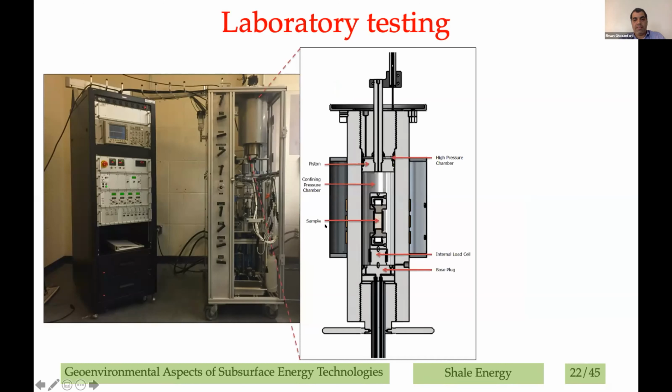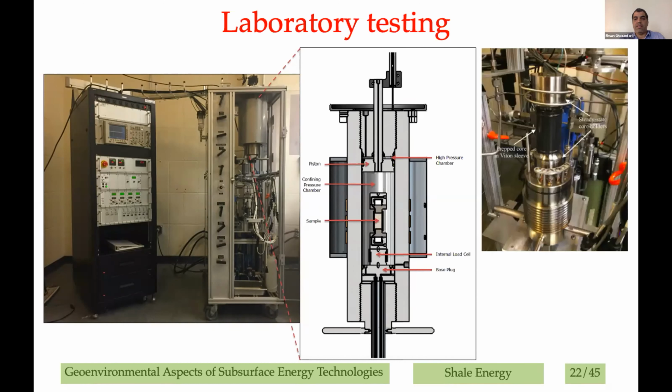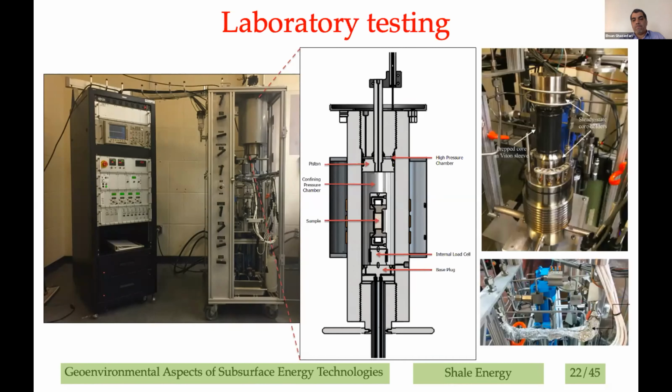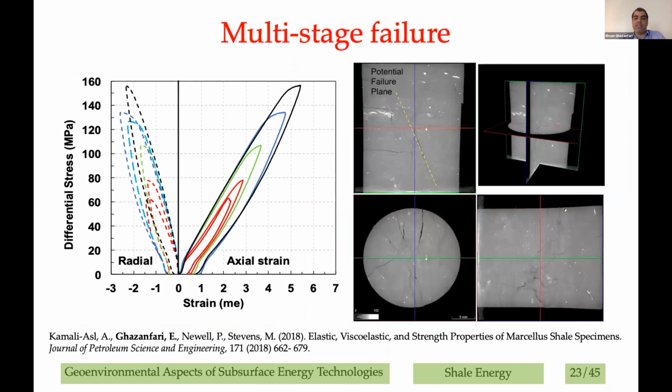So it's similar to a typical triaxial setup where you subject the specimens to confining pressure and axial pressure, and there's also pore pressure, but with higher pressures so that you can study relevant conditions in the lab. These are images of how you can set up the specimen and how you can wrap the piping to simulate the higher temperatures.